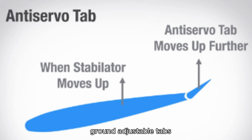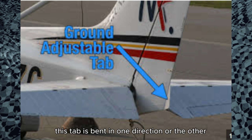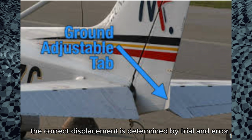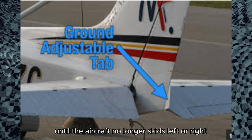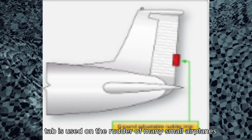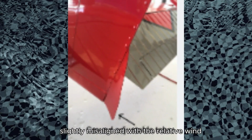Ground adjustable tabs. Many small aircraft have a non-movable metal trim tab on the rudder. This tab is bent in one direction or the other while on the ground to apply a trim force to the rudder. The correct displacement is determined by trial and error. Usually, small adjustments are necessary until the aircraft no longer skids left or right during normal cruising flight. A ground adjustable tab is used on the rudder of many small airplanes to correct for a tendency to fly with the fuselage slightly misaligned with the relative wind.